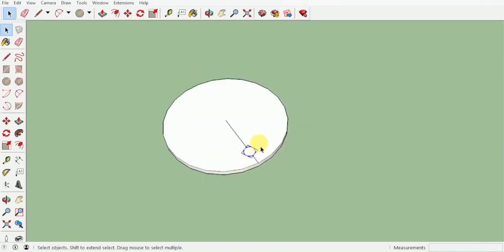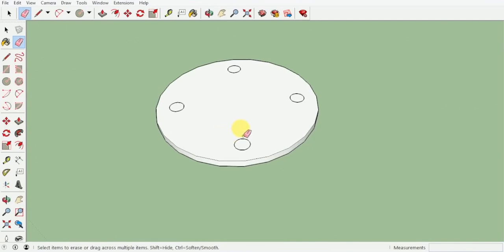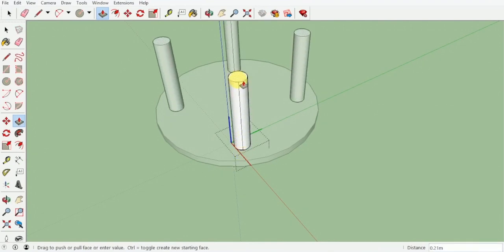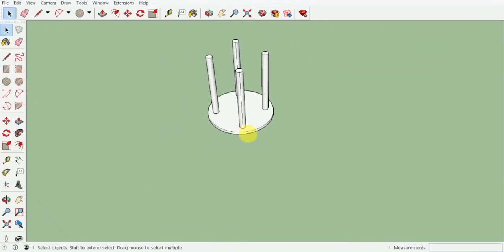Once I've created the component of this circle, I will use Q, which is the rotate command. Then I'll make the axis of rotation as the center point. Pressing Ctrl, I will copy this circle on the side at 90, enter, and then of course *3, enter to have it array copied in the rotation. After this, I will erase these lines off, enter into the group, enter into the component, and pick up my legs like this at 0.45, enter. And now I can exit the group.